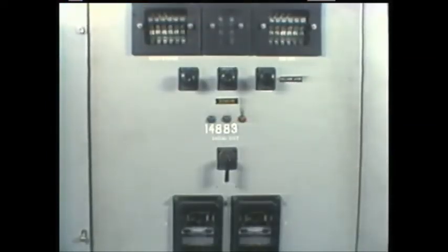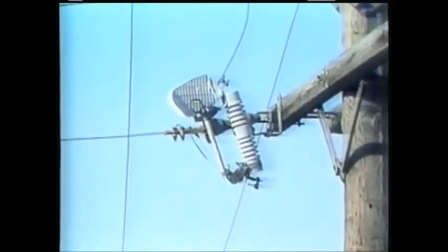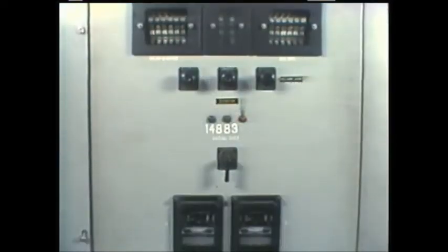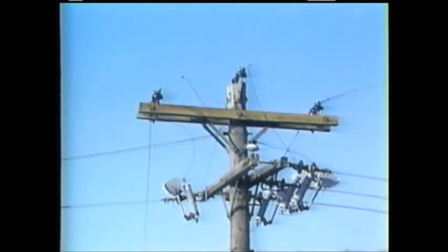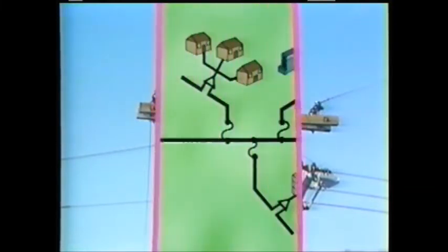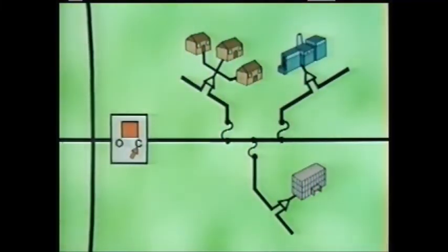Unlike circuit breakers that can open and close automatically, a fuse is designed to open and remain open whenever the value of the current carried by it exceeds its design capacity. In most distribution systems, circuit breakers and fuses are designed to work in a coordinated manner for system protection. We'll use a simplified drawing of a feeder with fused laterals to see how this coordinated effort is achieved.